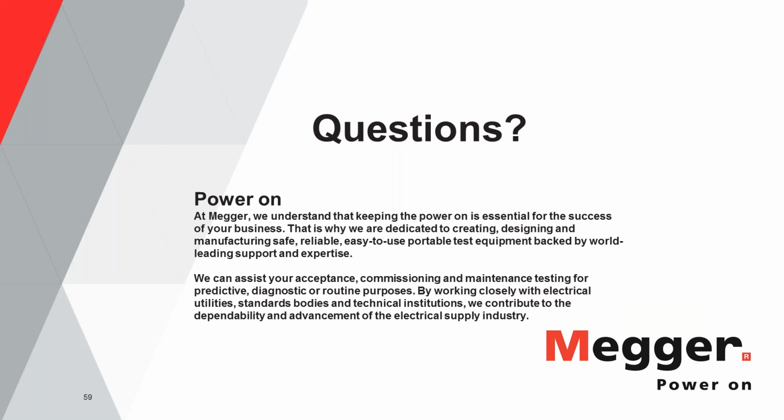To your question, is it recommended to perform the test at rated voltage? That kind of test would be destructive, because then you are doing the test at both high voltage and high current. That's the reason why in the factory at the OEM, in a full batch, they would randomly pick a few breakers and test at rated voltage and rated current to make sure that the insulation is of the right strength, the poles are separated apart, and they can handle the current.